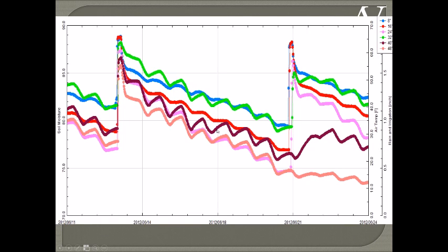Also, you see the stair steps, but you also notice it's kind of more of a sawtooth here. When you see that, it generally indicates you have a lot of moisture in the soil, because even though they're irrigating here, this was done in June of 12. I got them to stop irrigating so much in 2013, and we didn't start irrigating until late July, early August last year, because we realized by looking at this, I can interpret this to say that there is moisture coming from other areas.